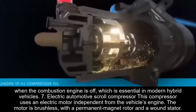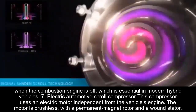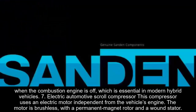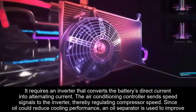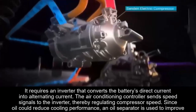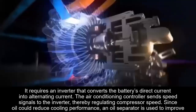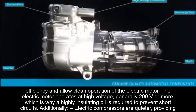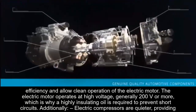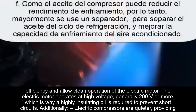7. Electric automotive scroll compressor. This compressor uses an electric motor independent from the vehicle's engine. The motor is brushless, with a permanent magnet rotor and a wound stator. It requires an inverter that converts the battery's direct current into alternating current. The AC controller sends speed signals to the inverter, thereby regulating the compressor speed. Since oil could reduce cooling performance, an oil separator is used to improve efficiency and allow clean operation of the electric motor. The electric motor operates at high voltage, generally 200 volts or more, which is why a highly insulating oil is required to prevent short circuits.